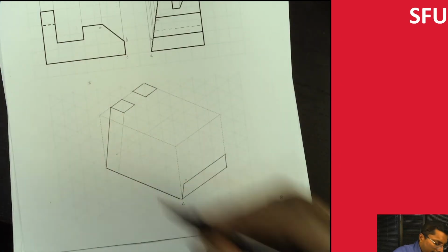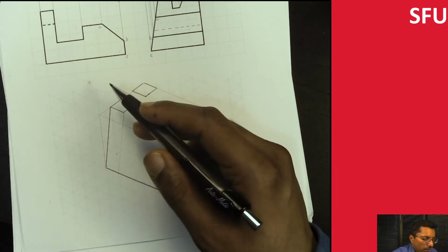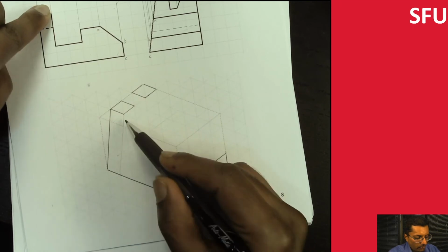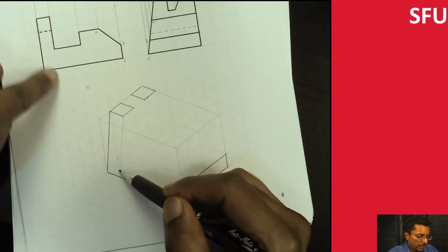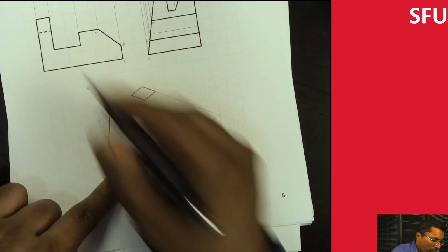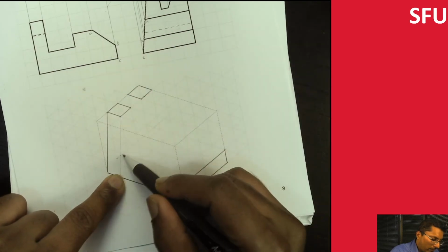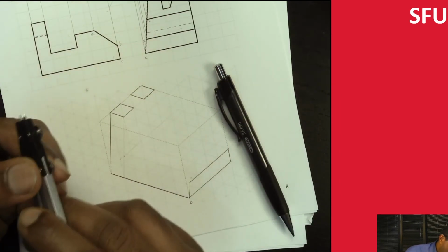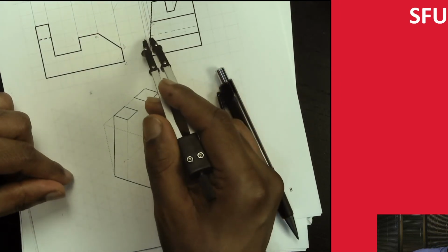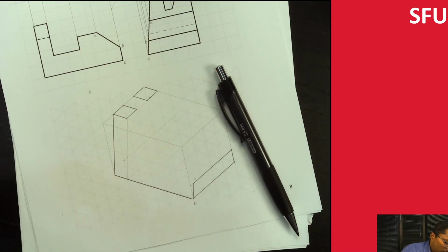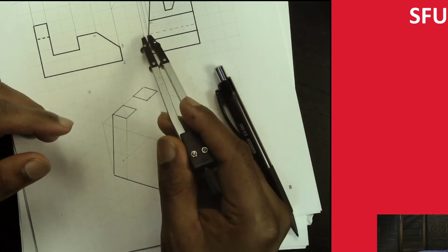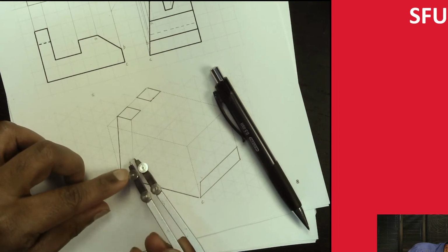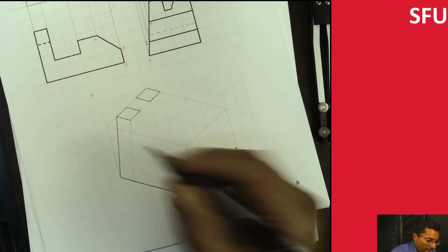There are a couple of ways you can actually do this. One way to do it is if you look at the drawing, you notice that this line and this line get connected. So I interpret that this is the same as this line, so wherever I intersect is going to be the point from where the line here starts. The other way to do it is to actually measure the distance from the right side view, or I can do it from the top view. So let's do it from the right side view. And I notice that this is not exactly equal to this distance here. So either way, I would actually end up getting the same point.